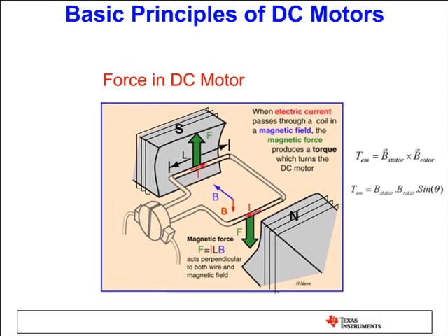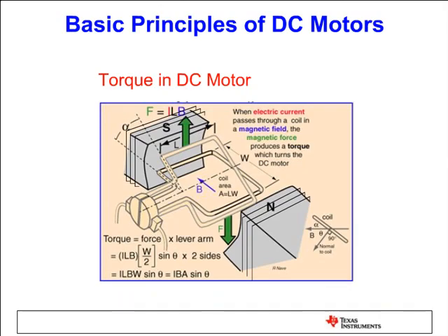So in FOC, basically, again, we are going to imitate this philosophy. And here's another picture when the rotor starts spinning. As you see, as the conductor moves a little bit, it's not aligned to the brushes anymore, and there is no path for the current. So it doesn't conduct current anymore. Only the horizontal ones can conduct the current.